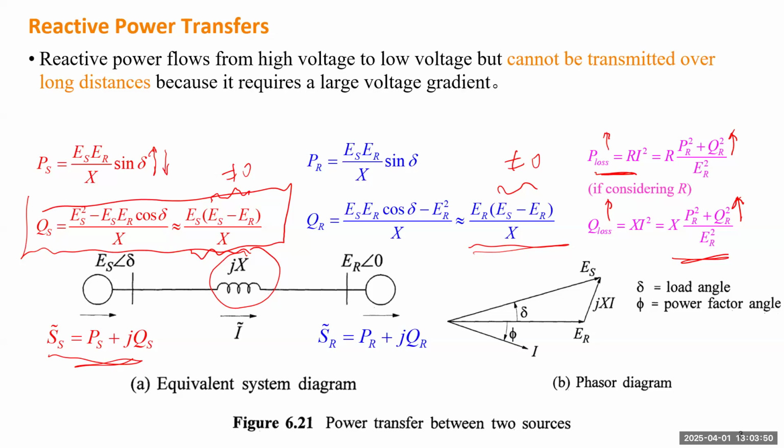Let's say 5%. For a distribution system, that 5% may increase to 8%, or even 10% in some areas, but it's still pretty small. Which means this gap at the most will give you about a 5 to 10% difference, and divided by the total reactance, there's a very limited reactive power you can transfer from one point to another point. So you have to utilize some other methods, not just generators. You cannot use generators to deliver reactive power to the entire network.